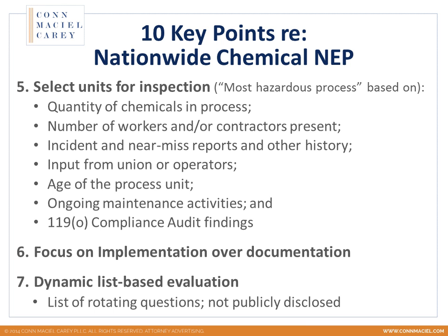If you've got problem areas that need more work than other areas, they're going to look at that and see if they're being adequately addressed from a mechanical integrity standpoint, whether your PHA has identified any unique hazards or unique issues because of ongoing maintenance issues. And then they're going to be looking at your 1910.119 PSM compliance audit, and that might inform them about certain units they ought to spend a little more time looking at.